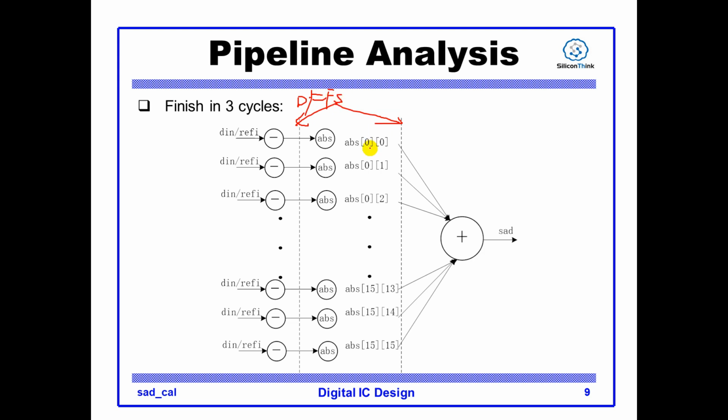This will be much better than the one before. Yes, 5 nanoseconds, 5.2, and 25. So in this design, the clock frequency will be decided by the delay of this part. That is about 40 megahertz.